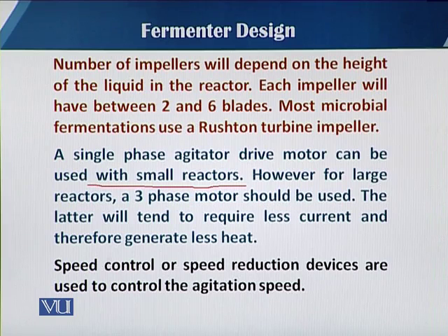However, in the case of large reactors, three-phase motors are mostly used, or should be used, because a three-phase motor generates less heat. When a motor is driven, heat is produced because of resistance. That is very critical, because the motor is attached very near to the vessel body.